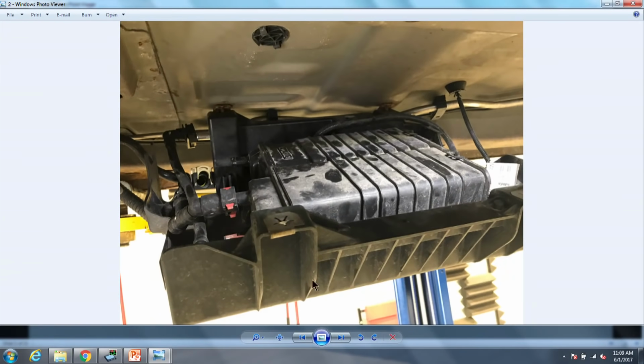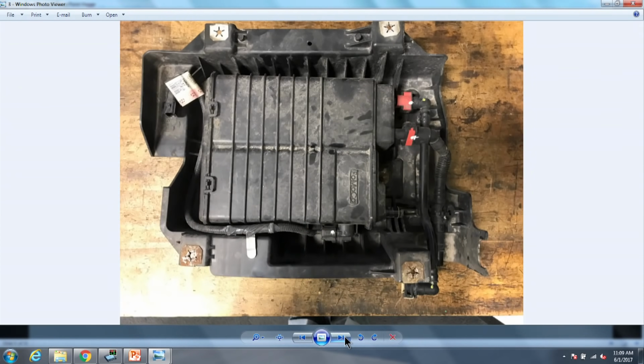So here's the canister on the Escape. It's got a nice little shield covering it. It sits just forward of the gas tank. I took the bolts down. You can see we've got some wire running here. This goes to a connector right here, which runs the wire over to our vent solenoid, which is on the other side right here. And then we also have some hoses connecting this thing to the gas tank and the filler neck. As I take it off and throw it on the bench, you can see here's that connector I talked about, running the wiring around to the vent solenoid right here.